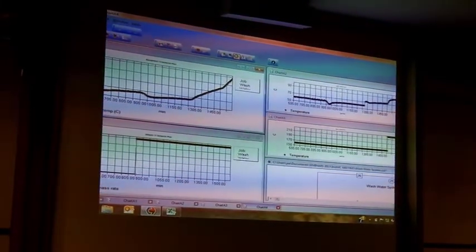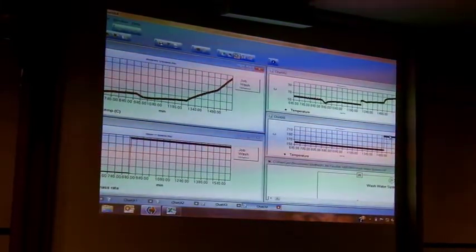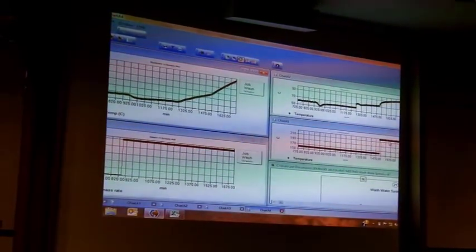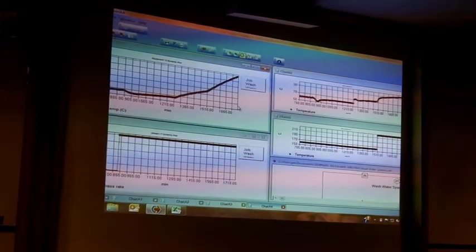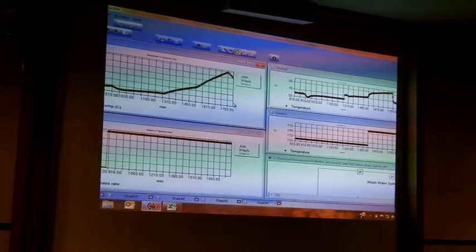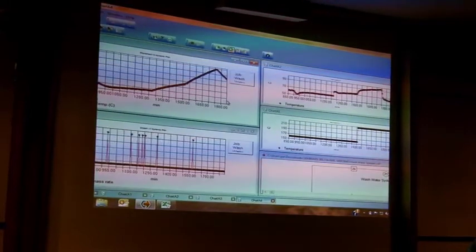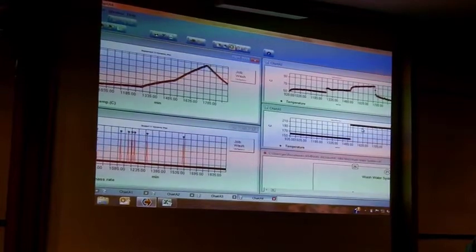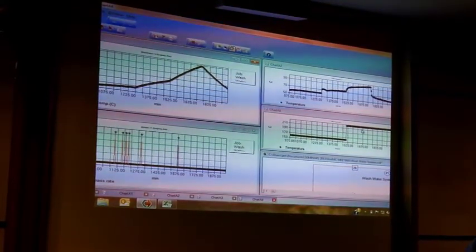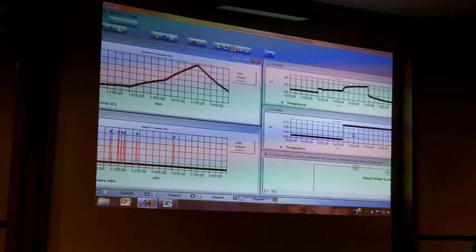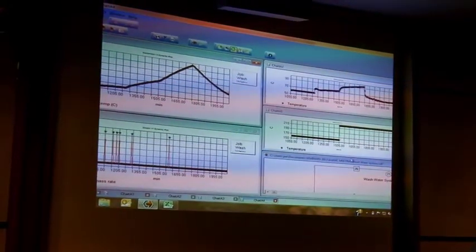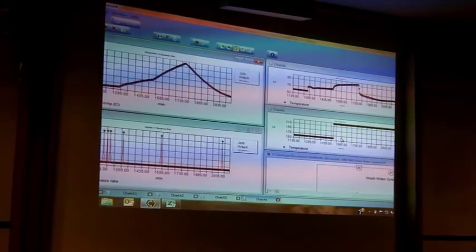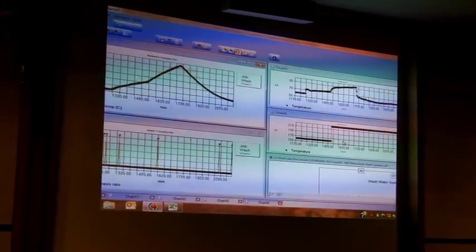This is the flue gas temperature changing. Actually, I've been very unkind because I failed the valve open at the same time as I hit it with the change in flue gas up to the maximum. So I probably wouldn't hit that 86 degrees C I showed you on the presentation. Imagine how long that would have taken with a 60s computer. I think you'd come back 2 days later.